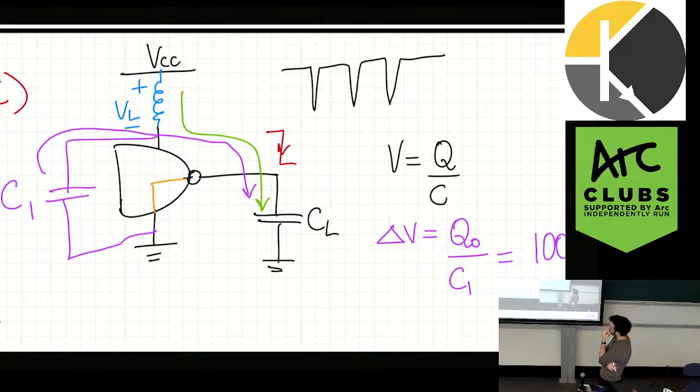What about VC1? Because we're interested. So you're not wrong. The pull up and pull down resistances will be different. But what happens to the voltage across VC1? Because that's what we're interested in, really. What is happening? Nothing. Does it need to charge up the capacitance anymore? What's happening to the charge across CL when we pull low? It just shorts. Just goes to ground.